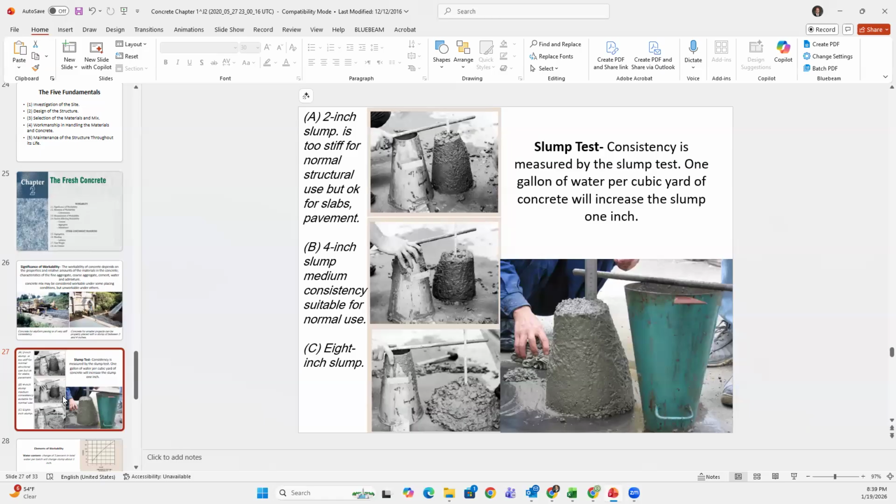The way it is supposed to be: the concrete truck comes in, and when they get to the project site, they roll their drum. The drum is not rolling on a freeway. You have all seen trucks with the drum at the back on a freeway. The drum is solid as they travel, but when they land at the job, they turn the drum once or twice to make sure the water and the aggregates get remixed. Remember, all this has to be done within 1 hour, otherwise too late.